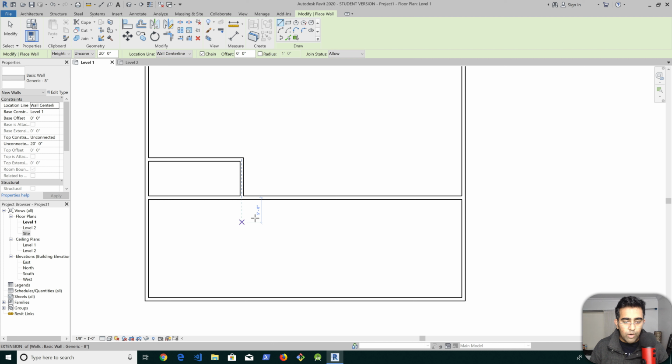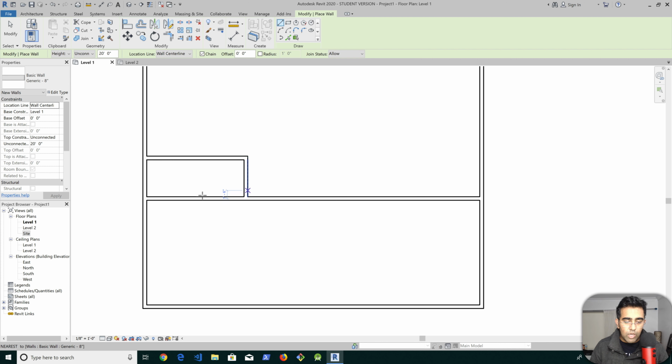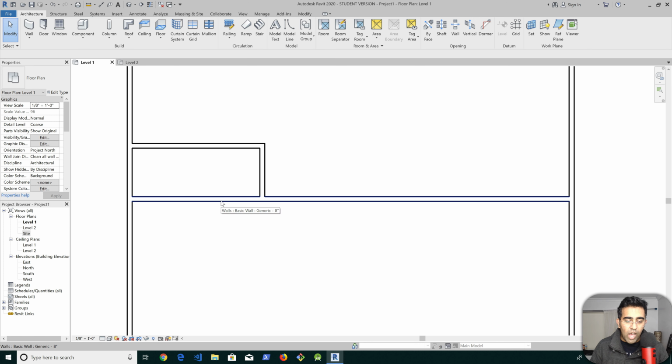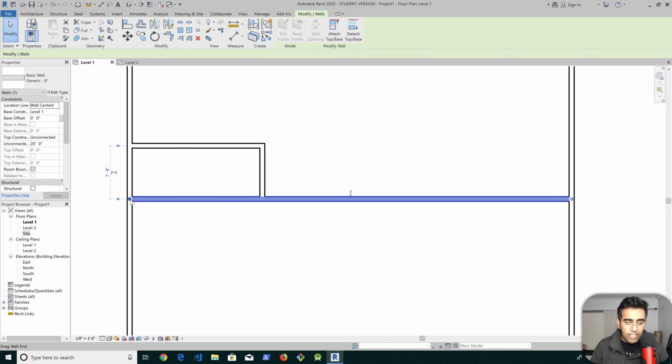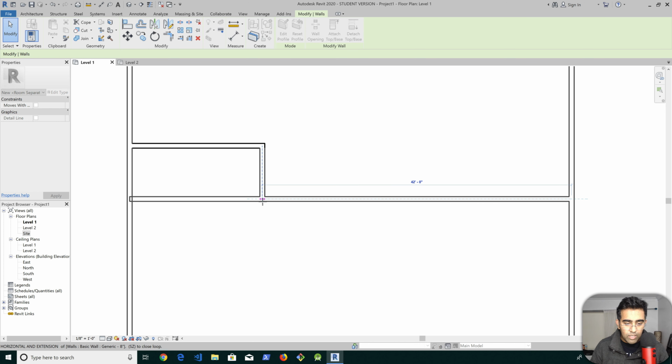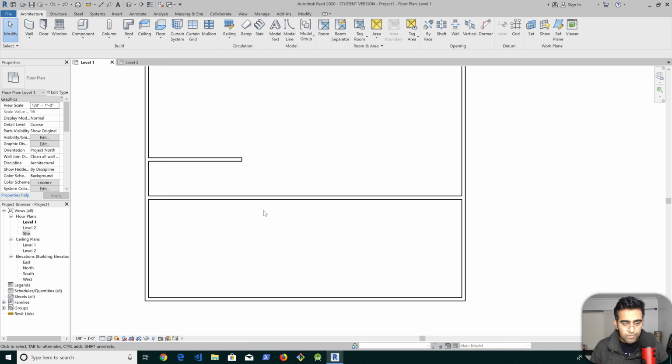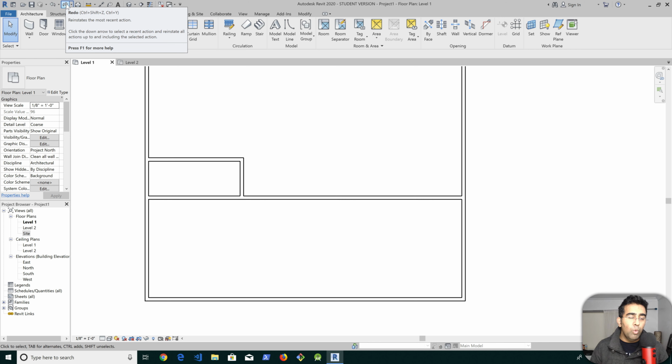Okay. Now, for example, you create this. Now this is going to be a garage, a car park. Okay. Now we want to remove this wall. How do we remove that? Now either you click on this circle, get it out, put it here, or I'm gonna press Control Z to undo. Whoops. We have a redo as well. So here are those options, undo and redo. So undo basically gets you a step before. A redo will reinstate the most recent action.